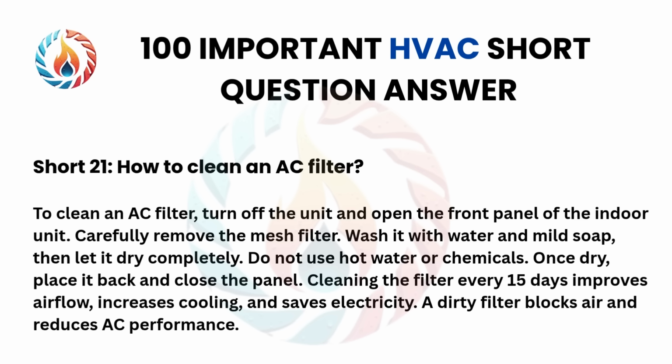Short 21. How to clean an AC filter. To clean an AC filter, turn off the unit and open the front panel of the indoor unit. Carefully remove the mesh filter. Wash it with water and mild soap, then let it dry completely. Do not use hot water or chemicals.